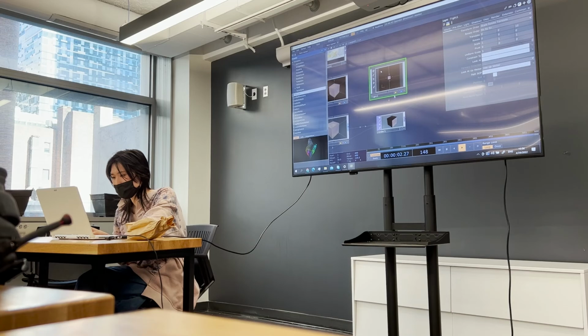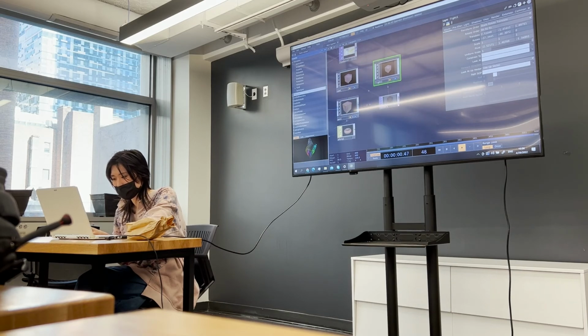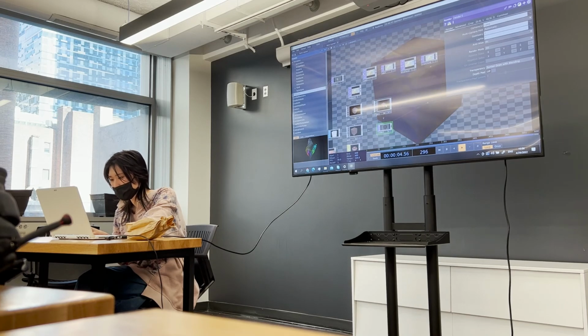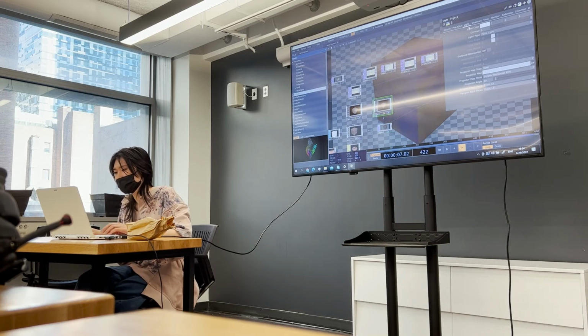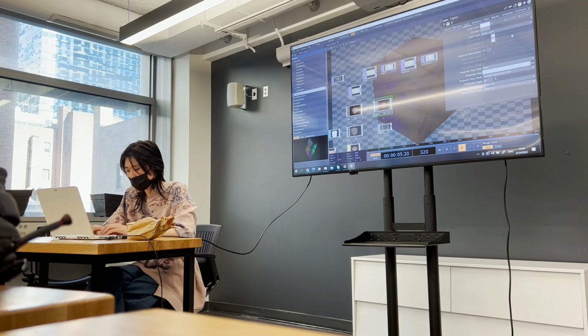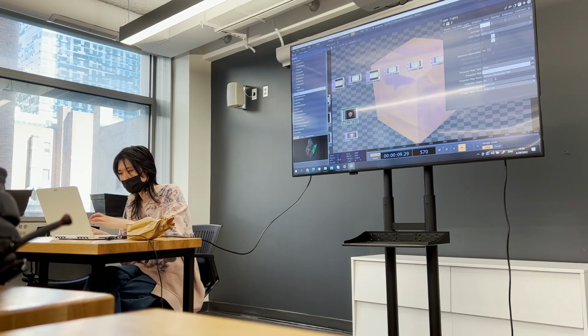And here, this also changes the light as well. So if you see, we got the camera, we want the light at the same angle. So we just change it to the same angle. And it's a little bit dark. Let me see. Yeah, a little bit dark. We can go to lights. Light, there's a parameter called light dimmer. It says maximum is 1. It's lying. Just type whatever value you want. Like 3, much brighter. Yeah.